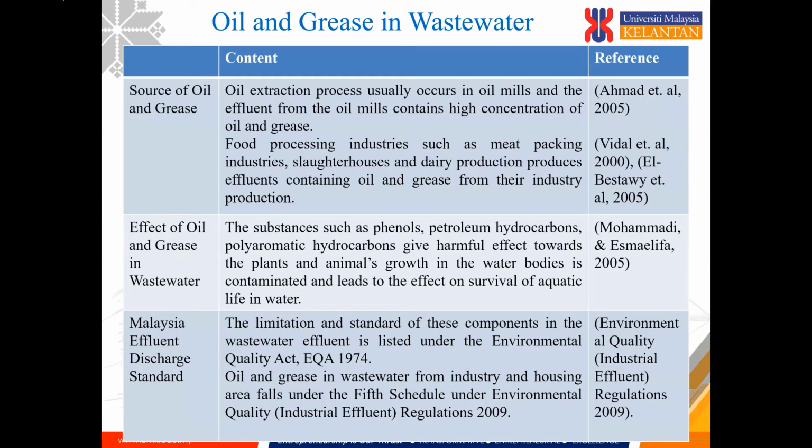The effect of oil and grease in wastewater is that it will affect the survival of aquatic life in water. In Malaysia, the limitation and standard of these components in wastewater effluent is listed under the Environmental Quality Act EQA 1974. Oil and grease in wastewater from industry and housing areas falls under the 5th Schedule of the Environmental Quality Industrial Regulations 2009.